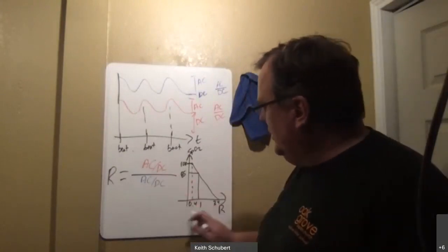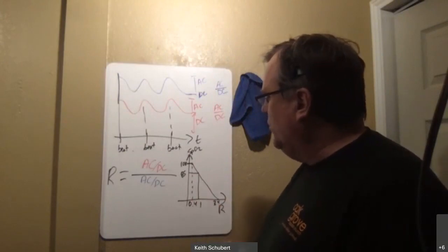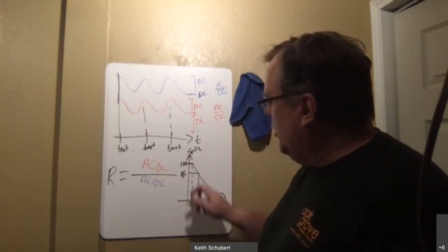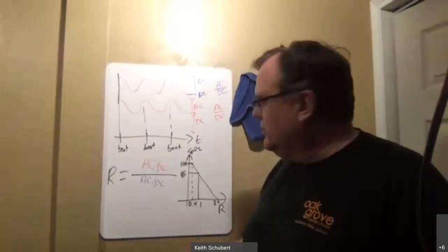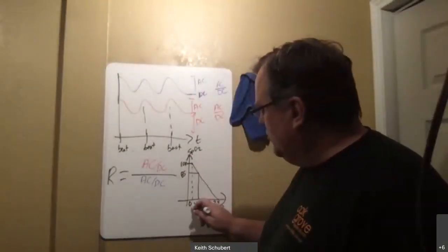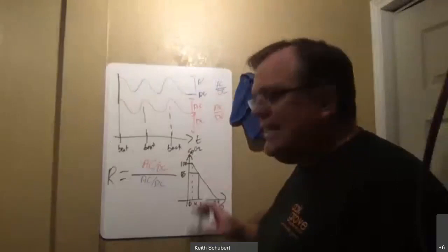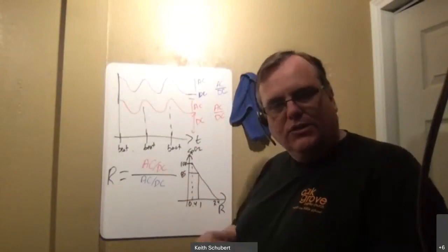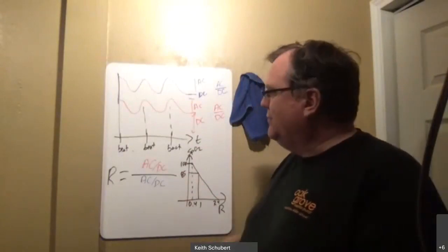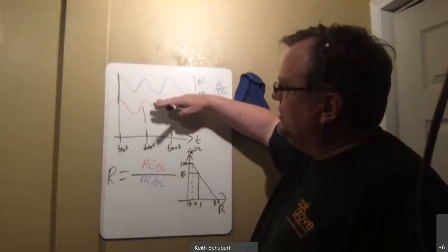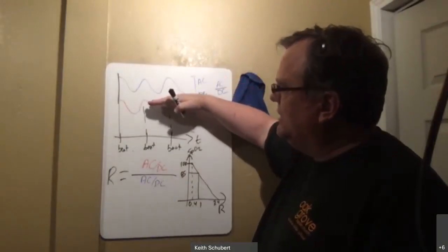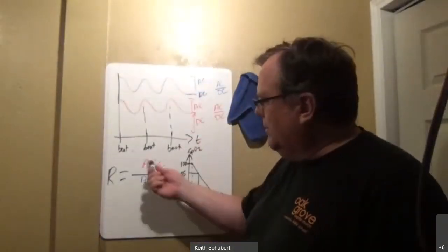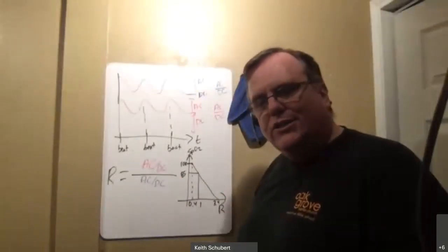So we would expect this ratio to vary between 0.4 and 1. And now that we've got 2 points, we've got a line, so we can convert from R to the oxygen saturation just by using a linear approximation between 0.4 and 1. And it will extend, so you can go lower if you need to. It turns out this is a much better way because it removes a lot of those unknown variables. If the light intensity changes, as it warms, you get less light out or it's less efficient, the whole curve drops, which means DC drops, so it's automatically accounted for. So light intensity variation doesn't matter.